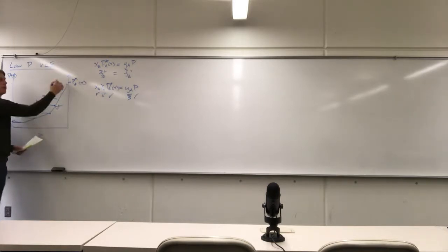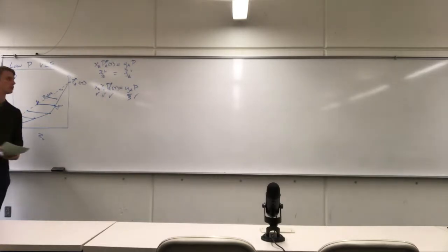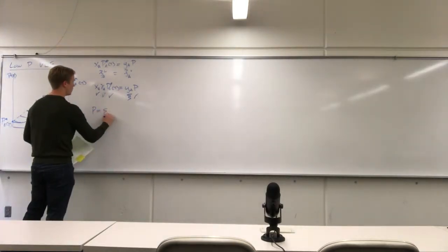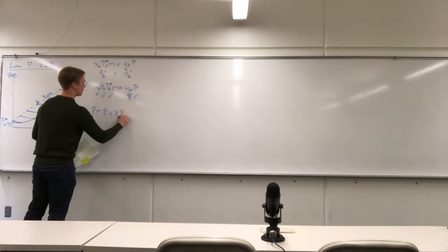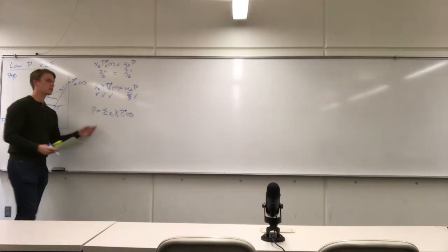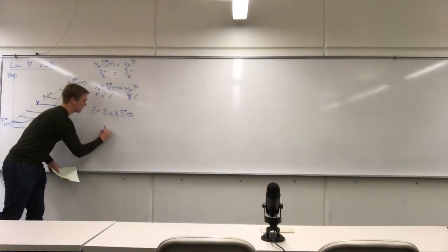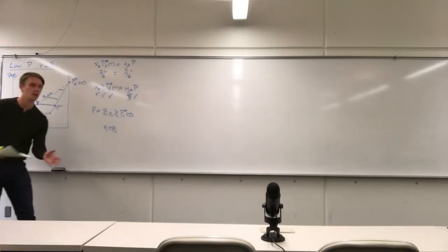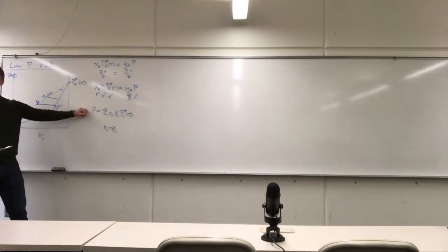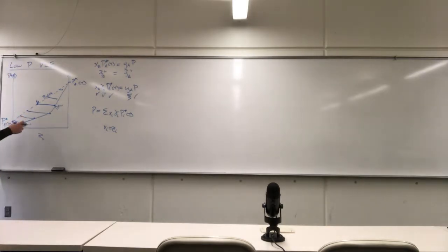So once we calculate the bubble curve, then we go through and do the dew curve. The bubble curve in this case here, we can calculate using this equation right here. Now this is not the bubble equation until the liquid composition is equal to the total composition. This is just any equation you can pull off the shelf and use for any circumstances you want for vapor-liquid equilibrium. Right? It becomes the bubble curve when we combine it with the fact that we know the total composition. So what we talked about, okay, is this clear, what we're doing here?